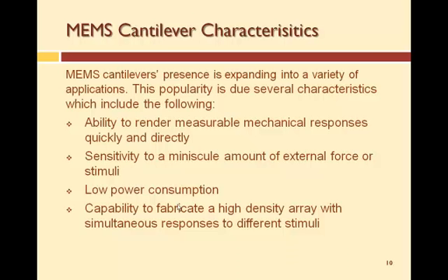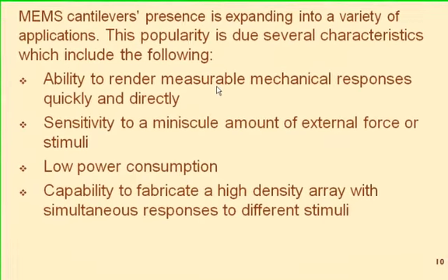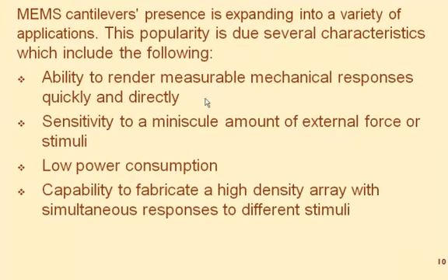So what are some of the characteristics of a MEMS cantilever? Well, you need to be able to measure something if you're going to use it as a sensor. And you can easily do that with a cantilever. You can measure the resonance frequency of it. There's different ways to do it. If you can measure how it vibrates and how fast it vibrates, you can use it as a sensor. And that's also part of the atomic force microscope cantilever. If you make the cantilever very small, you can also sense very small things. Makes it more sensitive.